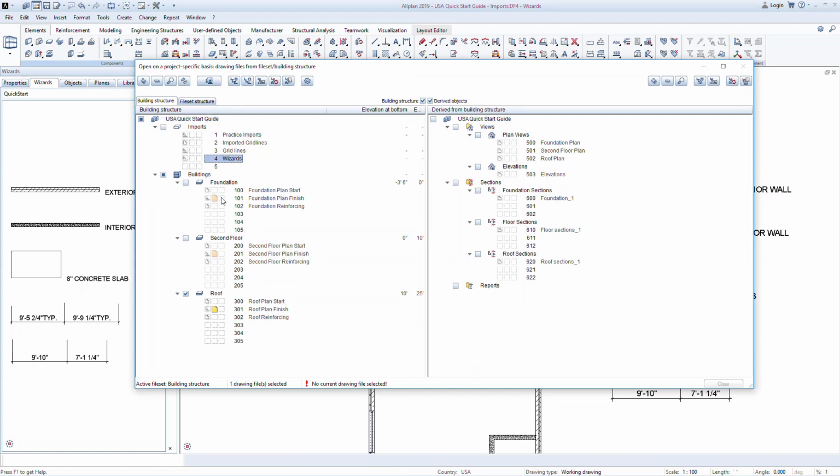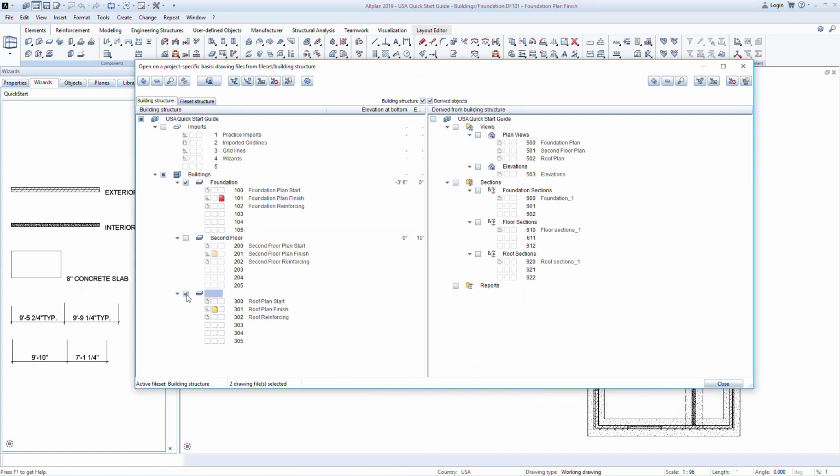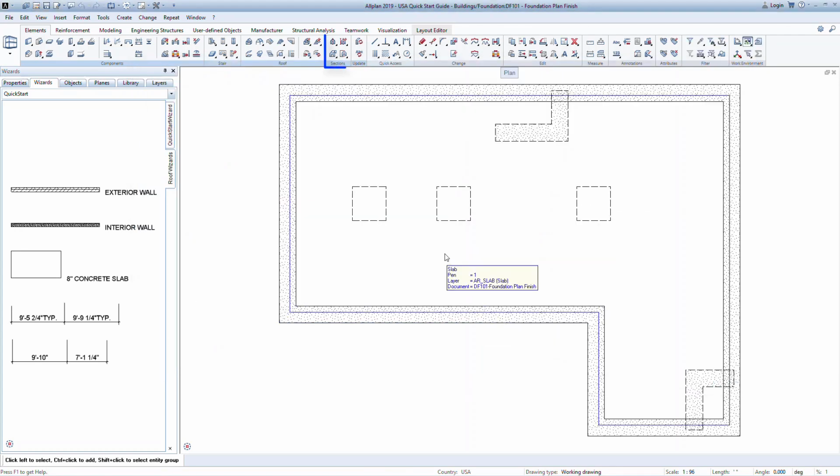Views are quick and easy to create in Allplan. These can be plan views, elevations, or isometric views. In the sections group of the reinforcement ribbon, click the black drop-down arrow to select the Create View command.